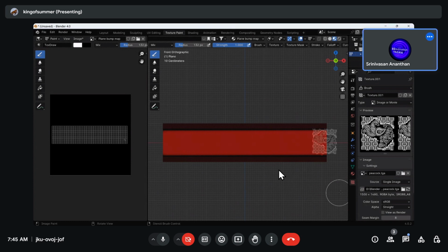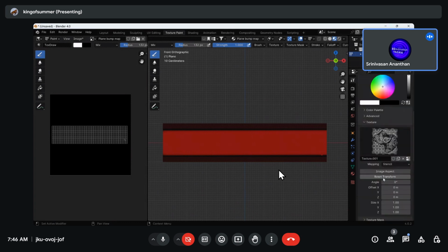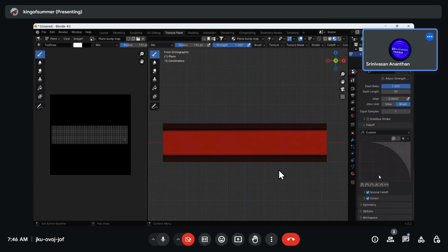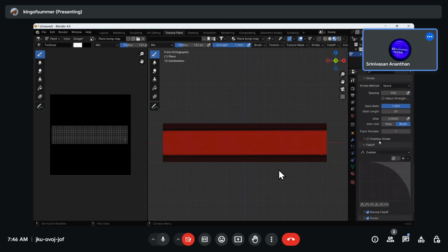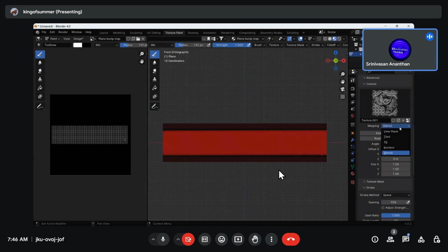Now go to active tool settings on the right top, first icon, left side. Now scroll down. Choose the stencil method. Go up. There you are, seeing stencil method. This is very important. Without stencil method, you won't be able to see the texture on the viewport.